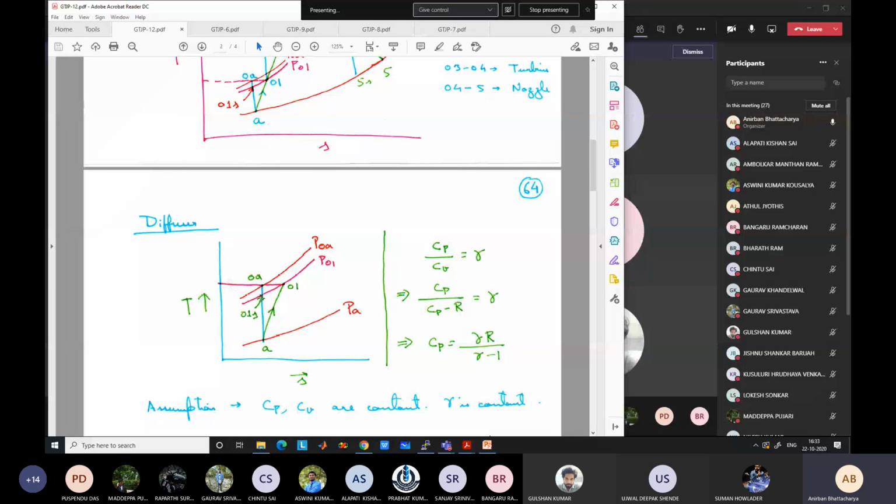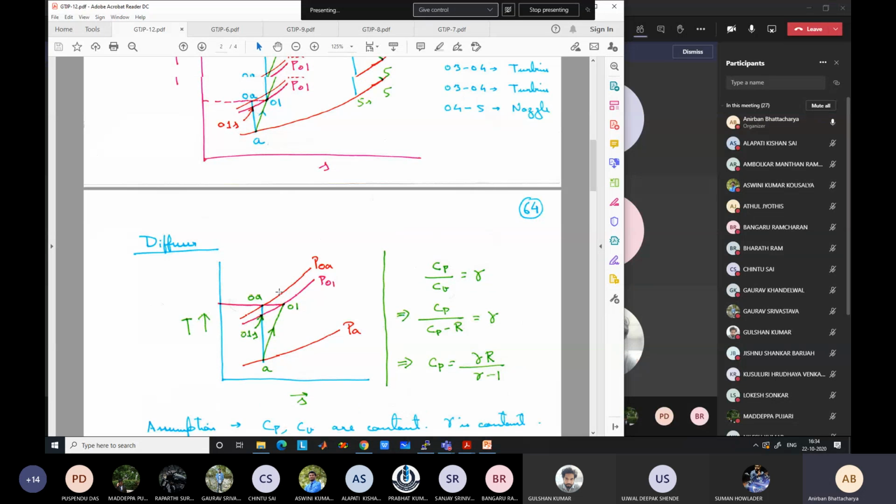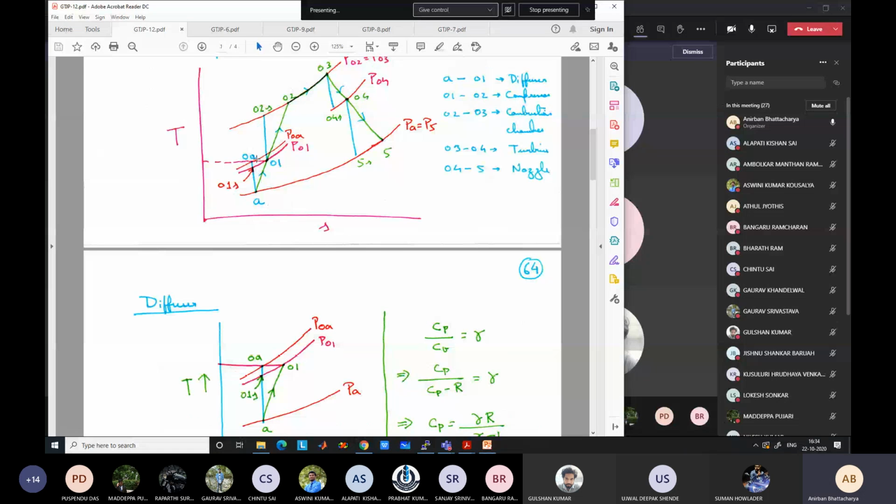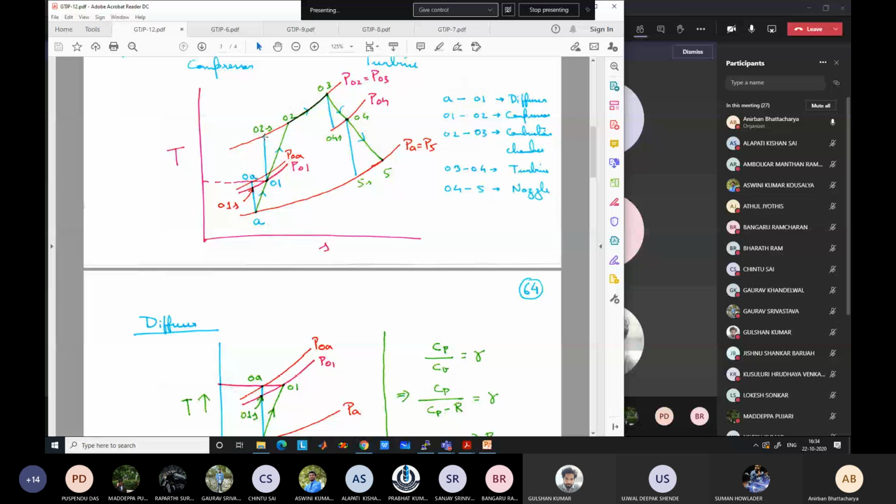The compressor is different as compared to the diffuser. See the compressor, the green line finishes at a higher temperature as compared to the blue line. How is it possible that despite losses temperature has increased in the compressor as compared to the ideal case, but not in the diffuser? All these are very fundamental things you should logically think about instead of memorizing. In the diffuser, our stagnation temperature could not increase, or did not decrease, even if there is a lot of friction.